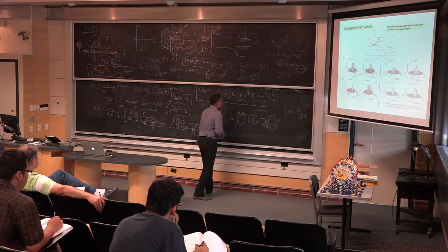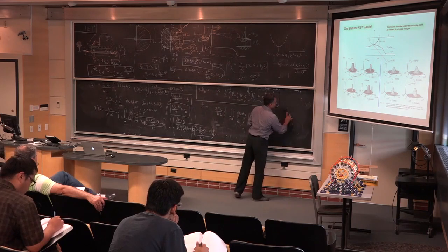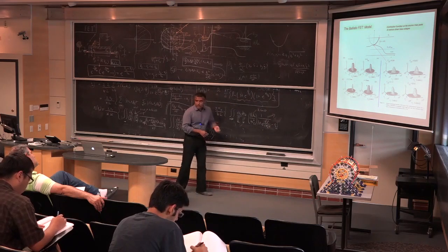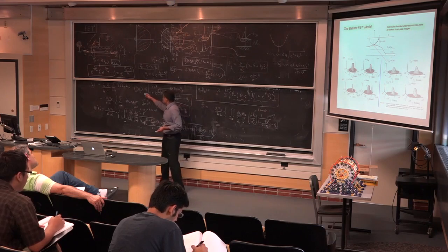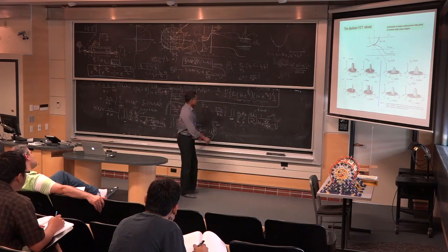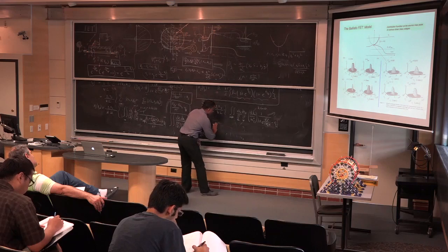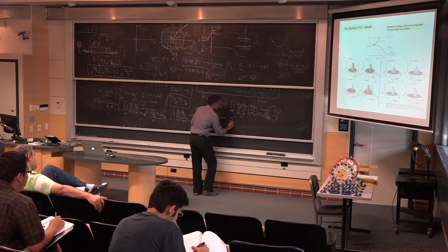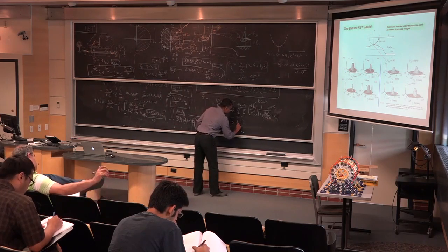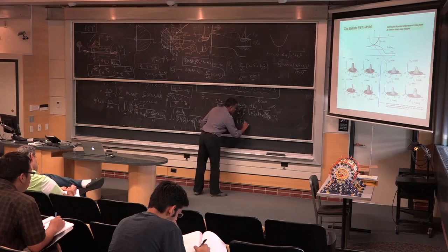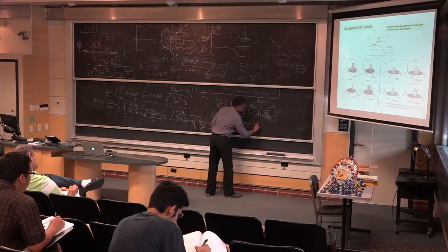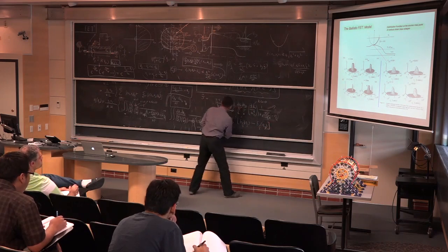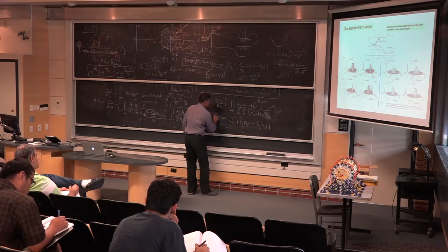And the half-order Fermi-Dirac integral is not exactly doable, meaning you don't have a closed, analytical form. So we just write it in that way, f of half. Just like we wrote f of 0 here, we wrote f of half. So when that is said and done, what you get is that the current will be J naught times f of half of eta source minus f of half of eta drain. So that will be the current in the transistor.